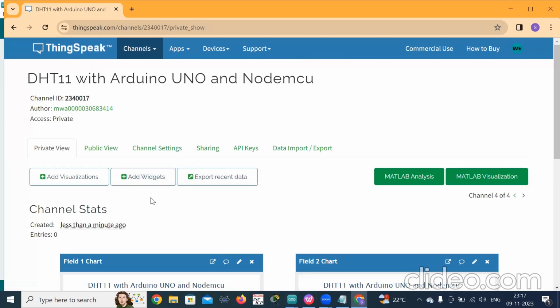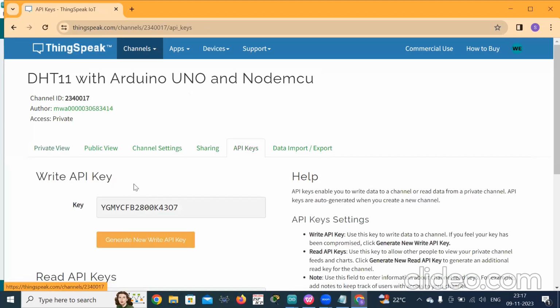After saving this channel, you should copy your channel ID and paste it in your program where I said, and click on API key. Copy this write API key and paste it in the program where I said. So these 2 steps you should take care of. After that, I'll show you how the data comes from NodeMCU into ThingSpeak.